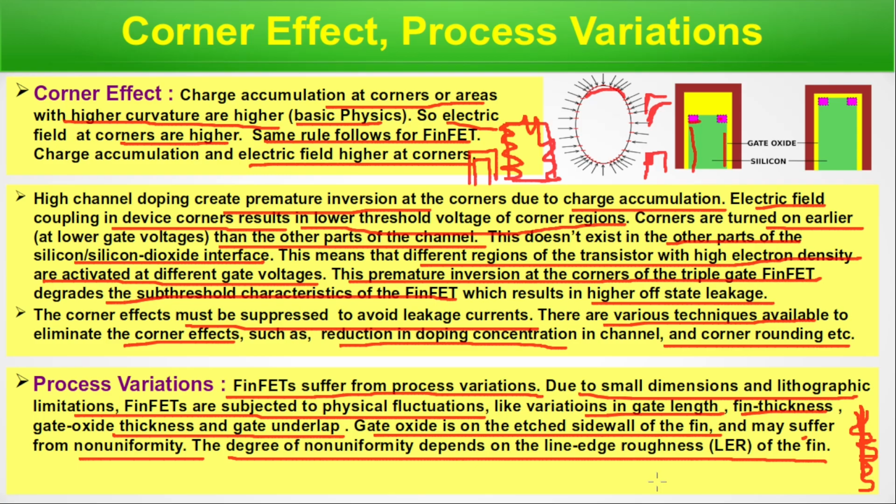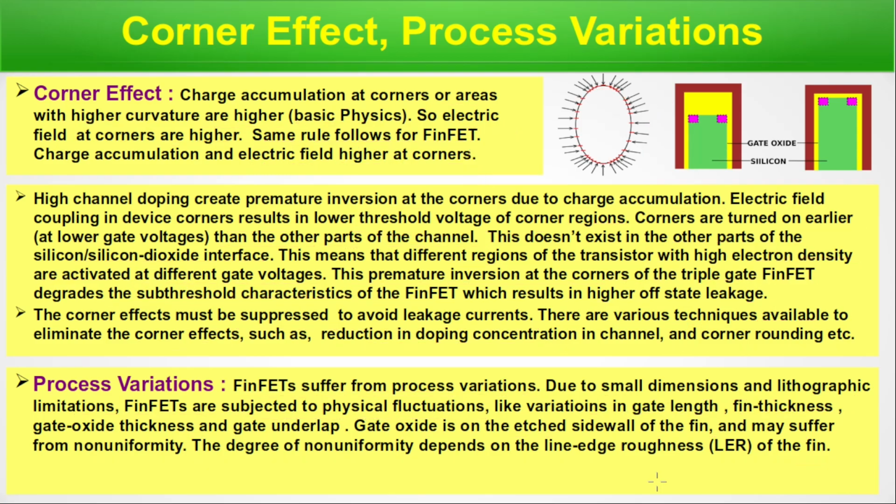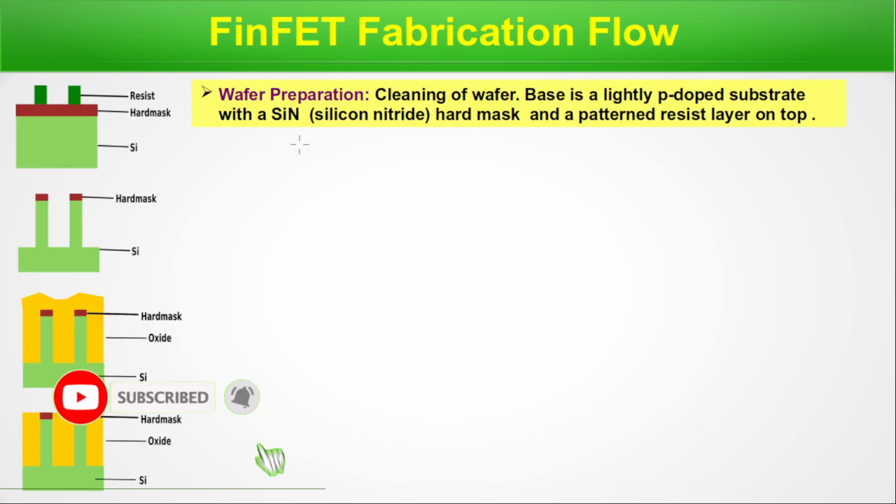We are done with this slide. We will move to the next slide. Now FinFET fabrication flow. So first, wafer preparation, and that includes cleaning of the wafer. Base is a lightly p-doped substrate with a silicon nitride hard mask and a patterned resist layer on top.